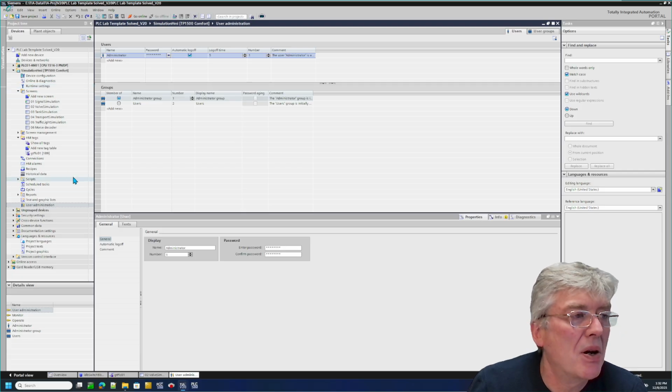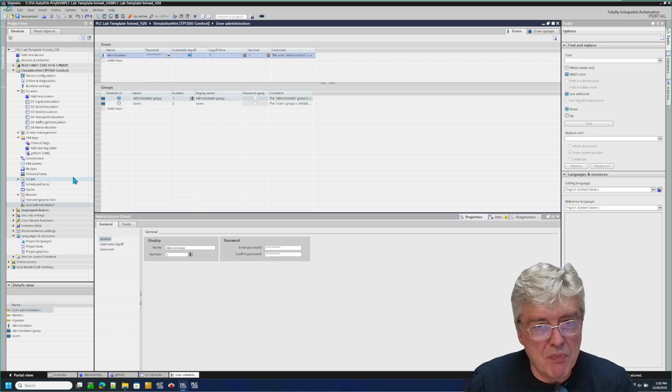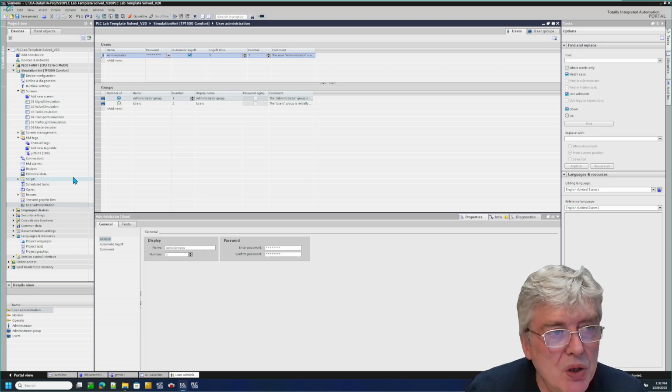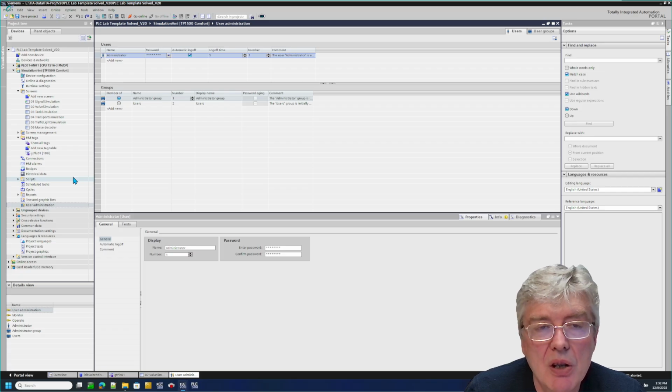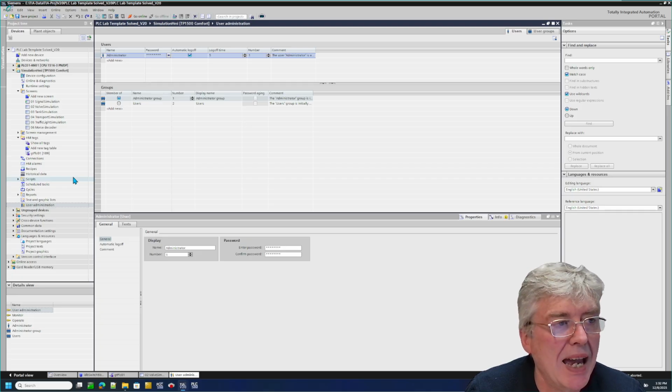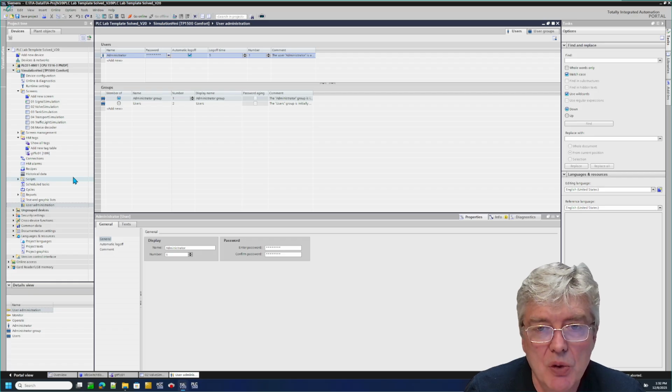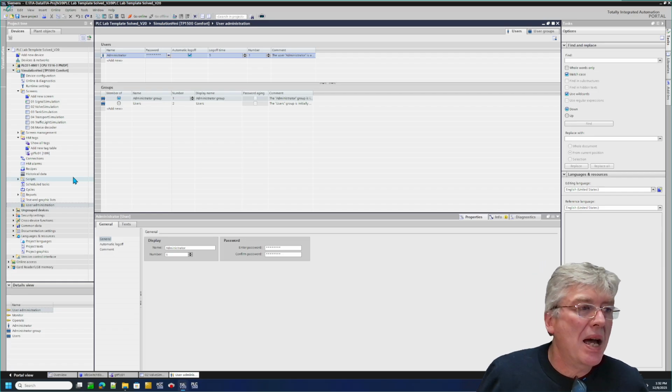Now it is possible to make something called pop-ups here, and you would need to have a pop-up for commands. So if you push a button, you have to have something called double commands that say, okay, you have to confirm that you really want to do this, or cancel. Nothing should happen just by pushing on a panel.